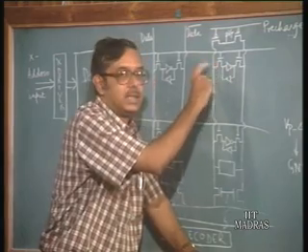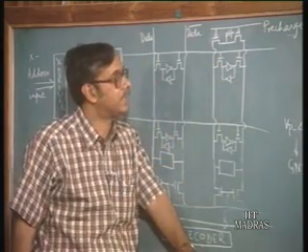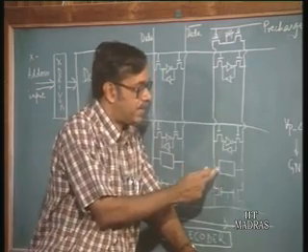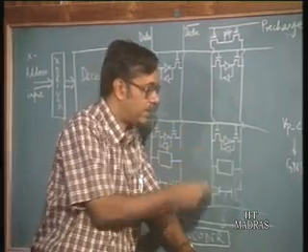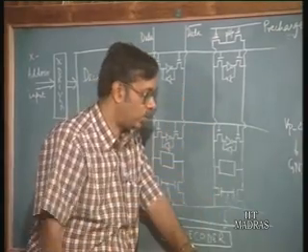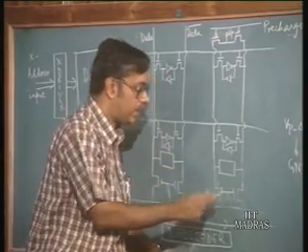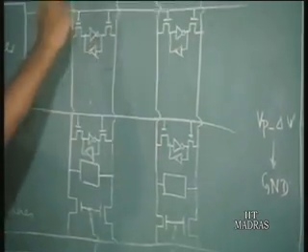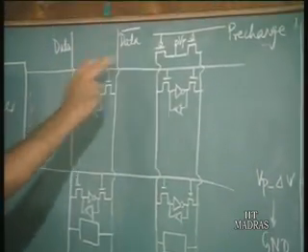So, once the small difference in voltage is created due to the cell voltage, the condition of the transistors in the cell, then the sense amplifier is turned on, which makes one of the data lines go high and the other one go low. This happens in all the columns, because one cell is selected in all the columns.